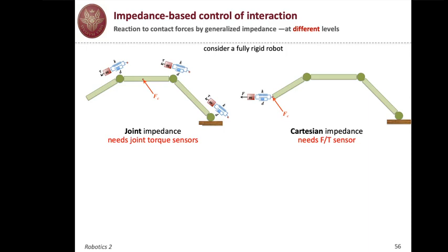And you can see that we can only consider a situation with a force applied there. Otherwise, this force will not be sensed if it's on the structure, because the force torque sensor is typically mounted at the end effector. We have seen that you can mount it also at the base, but this is a different story. Nobody has tried this type of operation with that sensor, at least so far. So you see that when moving to impedance, with a desired changed apparent inertia, you need sensors.